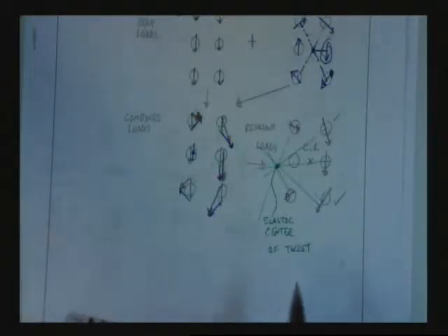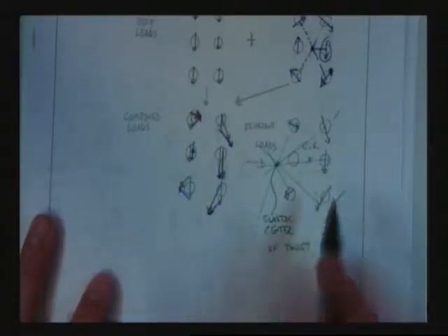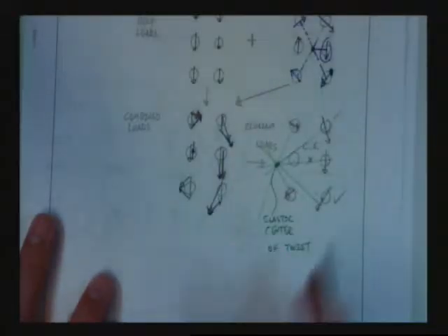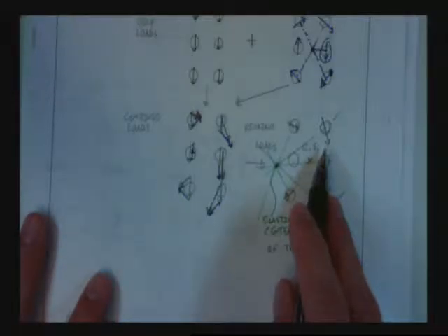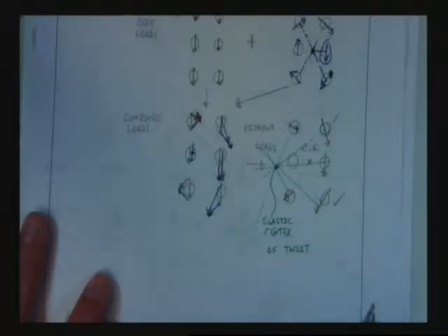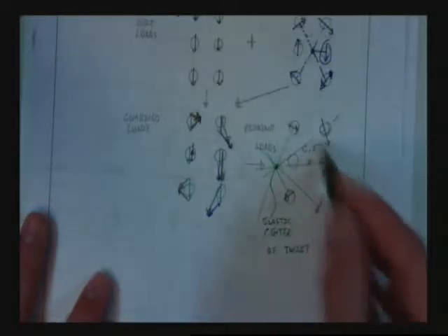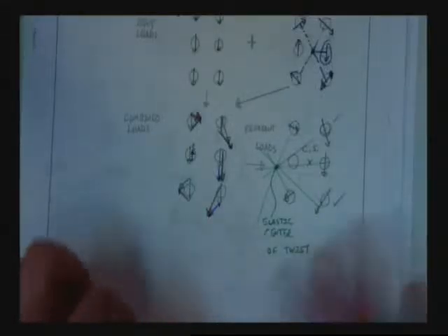Because you probably don't realize this or think about this, but we're assuming if this is our limit state, then as soon as one of these bolts reaches its limit state, we have to stop, right? We have to stop because we don't really know what to do. But we know that's not right. We know that structural resiliency tells us that even though one bolt reaches its limit, we can keep going, right? Keep going till what? Either all the bolts are at their limits, or until one bolt gets so overloaded that it fractures, right? It breaks on its own. Great. We know that's what's going to happen.